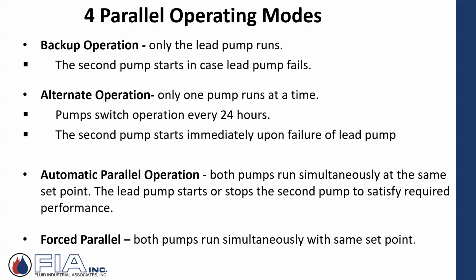So you could actually back off one of them and just run on the single pump because that can carry the load. And then as the load increases, that lead pump senses that change in pressure, what's going on in the system, and he brings the parallel pump back on, and the two of them are running together in parallel. So there's a lot of intelligence all on the same pump. And then the last mode is just force, where there's none of this logic, if you will, and they both just turn on and run all the time.